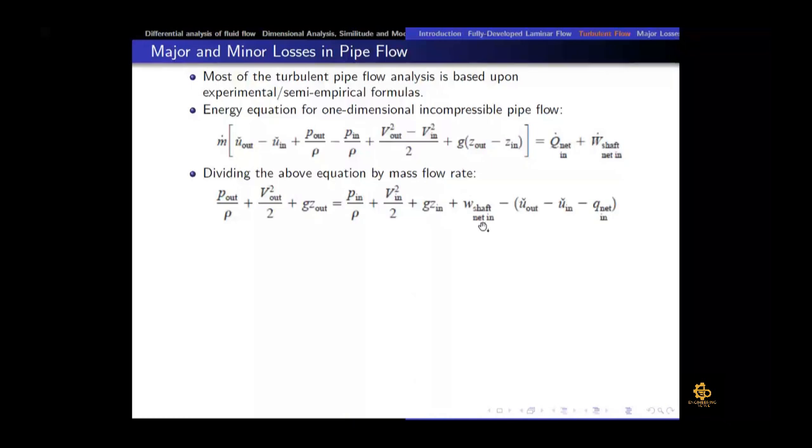And the second consequence of friction, as you have discussed in thermodynamics, is that the actual pump work is more when there is friction involved. That is represented by isentropic efficiencies. If you remember the TS diagram for the steam power cycle or gas power cycle, the concepts of pump isentropic efficiency and turbine isentropic efficiency include the frictional effects. So the consequence of including friction for the pump is that the pump work required is more, and the turbine work which we get out of that system is usually less.